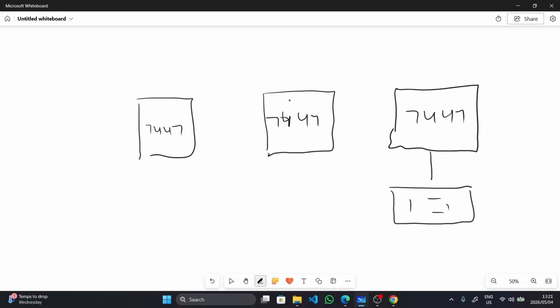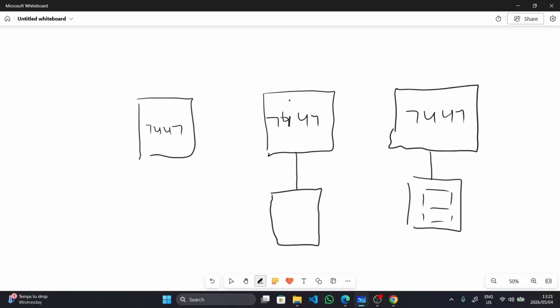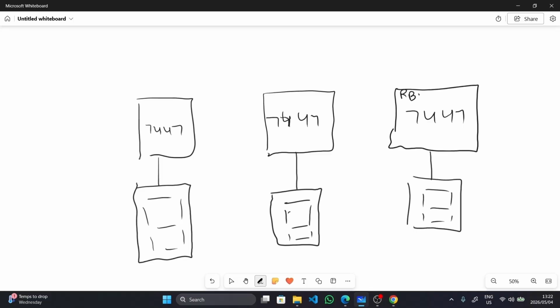And you have your, let's just say, 7 segment here. Then you have 3 7 segments. You have your 3 7 segments, and to connect them, you have your RBI pin. It goes to your BI or RBO pin.